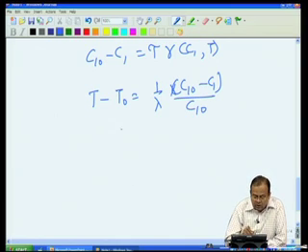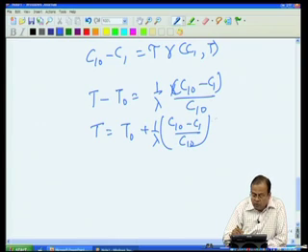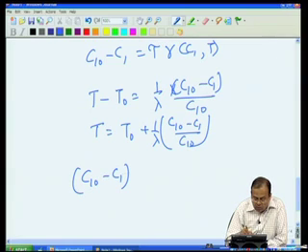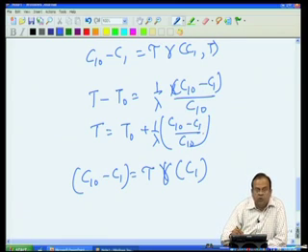In other words, I can write temperature, both in the case of the stirred tank reactor and the plug flow reactor, in terms of concentration alone, and thereby my mass balance equation is simply a function of R of C1, because I can eliminate temperature in terms of C1.